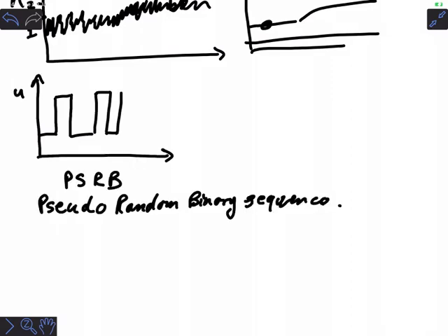An important property of these kinds of sequences, I want you to see: these kinds of pulses or random pulse tests are a lot more acceptable in terms of the disturbance on the plant. So for instance, back to the car analogy, that would be like driving a new car and just twitching the wheel a little bit and bringing it back, just to get a feel for how responsive the car is.